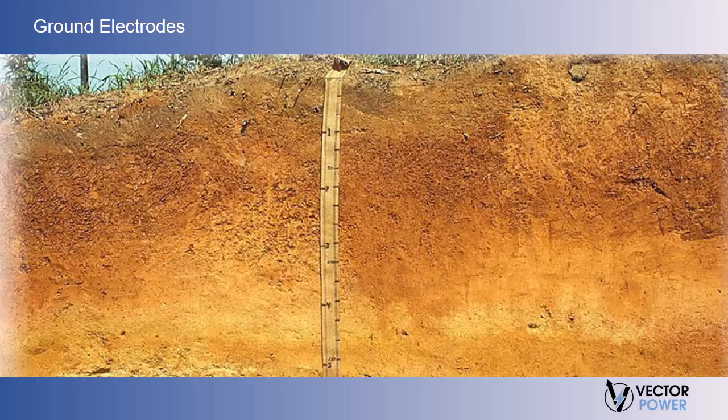In the case of ground resistance, uniform soil resistivity throughout the volume is assumed. However, this is seldom the case in the real world. The equations for electrode systems are complex and often expressed only as approximations. The most used formula for a single ground electrode system, developed by H.R. Dwight of the Massachusetts Institute of Technology, is as follows.